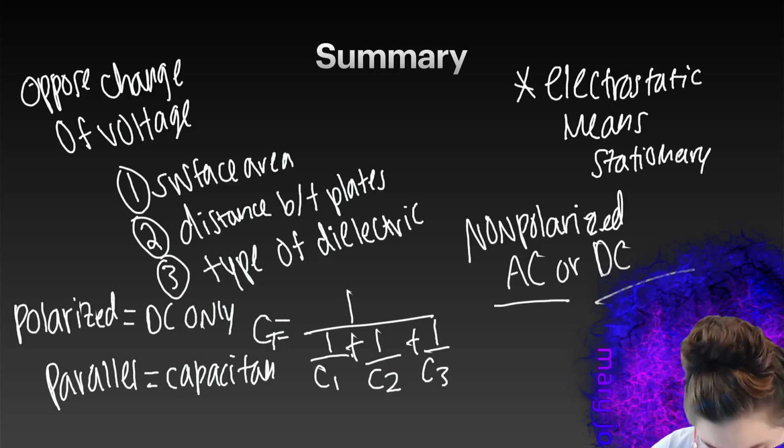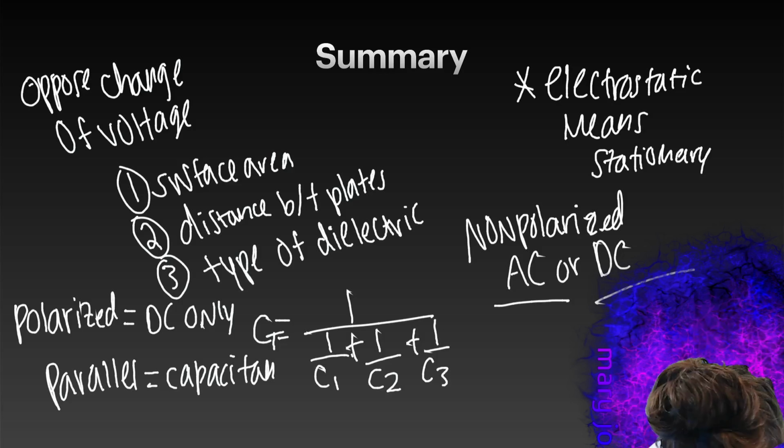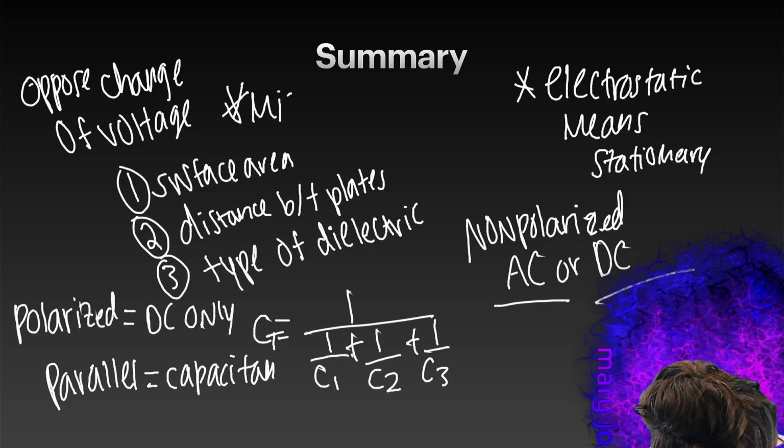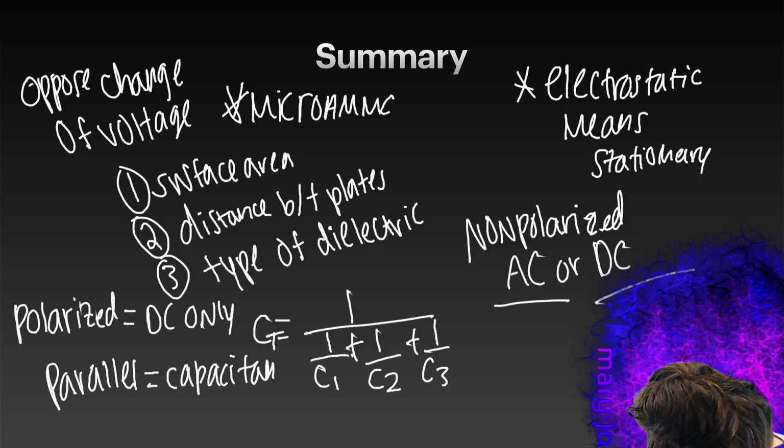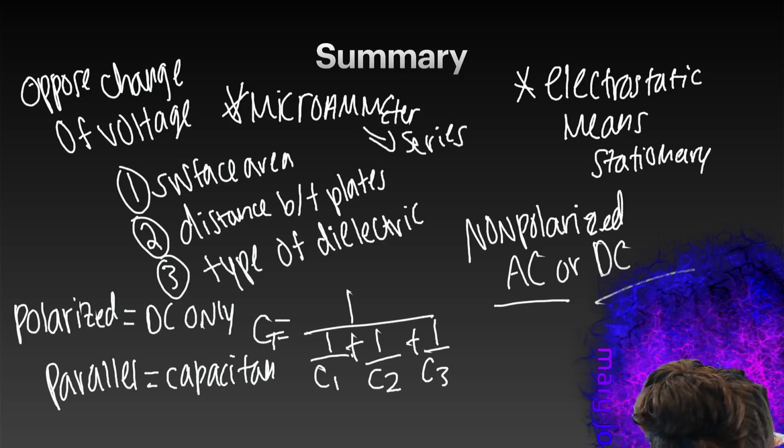The last thing is, if we want to test a capacitor for leakage, we've got to use a microammeter. And we've got to connect it in series with the capacitor and the voltage applied to the circuit.